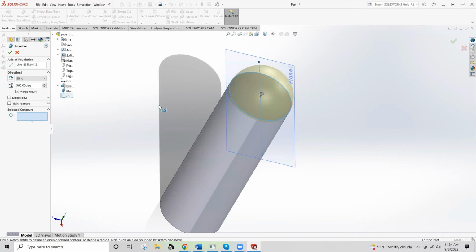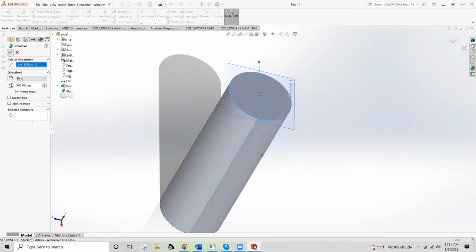So one of the questions that we are going to try and answer is, can we get this to revolve? And this line is this central axis, or this center line. That's our axis of revolution. So if we try and do this, we get errors. This self-intersecting problem is very frustrating and will come up a lot. And what I want you guys to do is pause when you see that error and think for a second about what it means with internal self-intersecting cross sections or center lines or whatever.